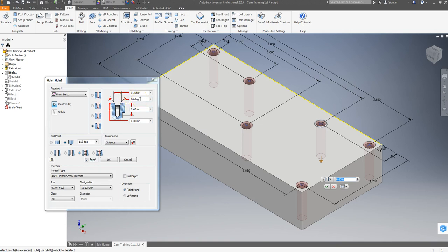We will be using in our tools a spot drill that's a 90-degree spot drill, so that's why this is 82. If it was a countersink for a flathead screw, American is 82 degrees and metric is 90. So it would be different, but this is just a little chamfer to create a nice edge. But all this information is here, and then if I were going to go and do a detailed drawing with dimensioning and hole callouts, I get all of this information for free. There are things that transfer over and automatically get recognized as a feature in the CAM portion of the software. So it is definitely worth it to do it as a feature, instead of just a point and then creating a whole feature.